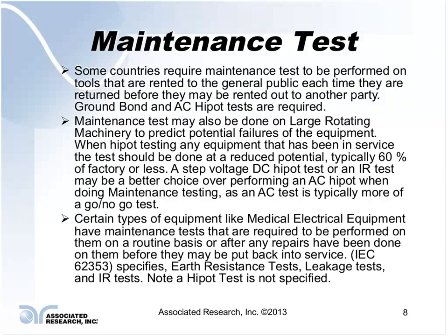If you're doing a step voltage test, monitoring the leakage current during each step, you can possibly predict a failure before it actually happens, looking for maybe a knee in a curve.